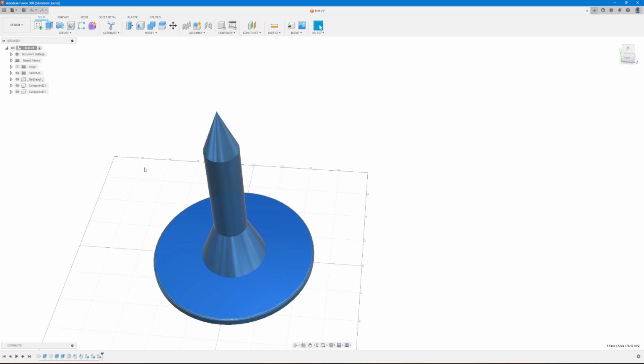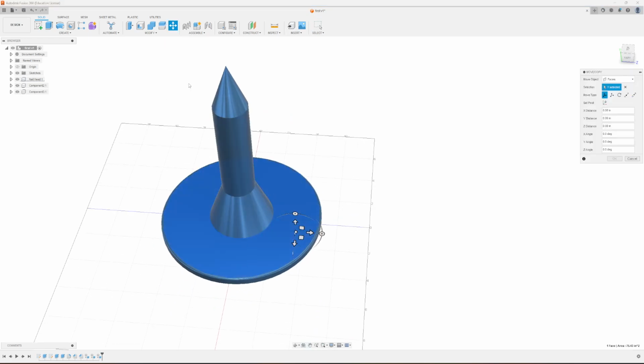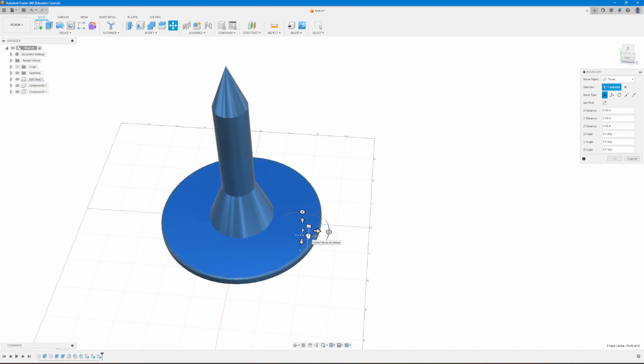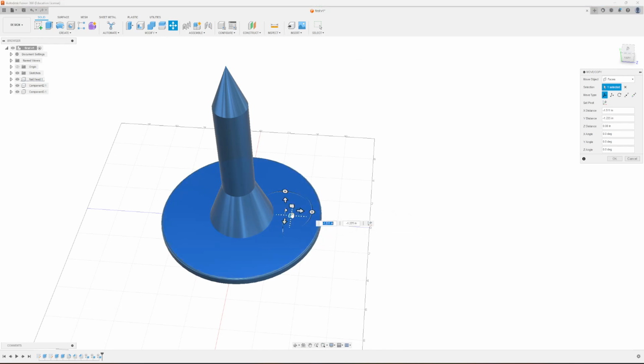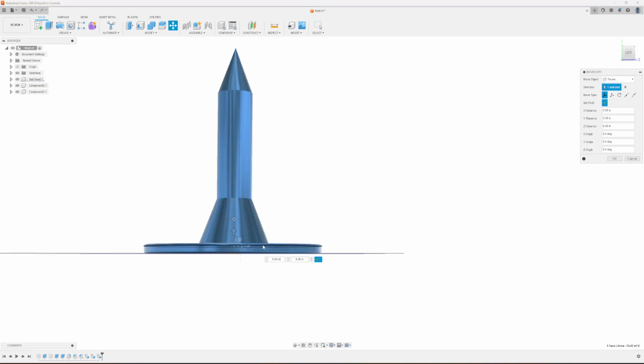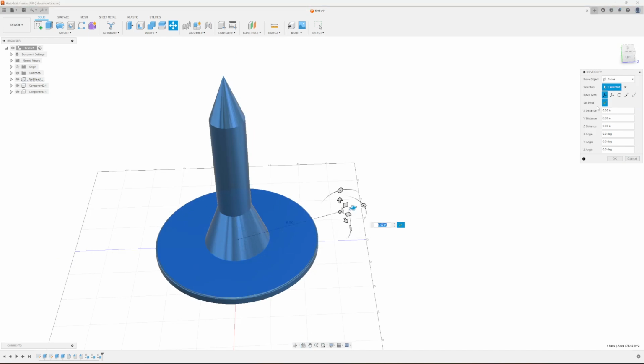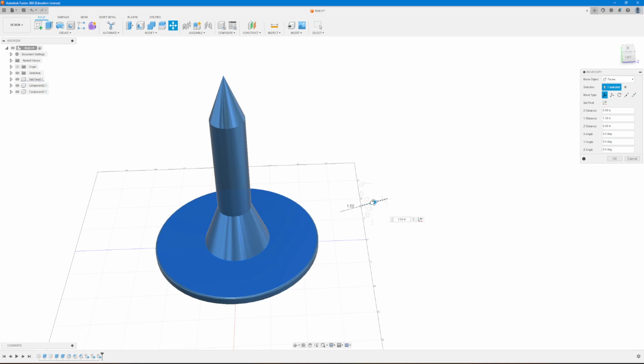All right, so let's move this object so we can do this with a moving thing. So the Move button up here, and we're going to click on the object. Basically, we're setting a pivot point when we do this. Click the pivot point here, set pivot point. Again, hold down Control if you want to snap to stuff. This is not being fun. There we go. All right, now move. Oh, goodness. You have to hit the check mark, and now you can move.